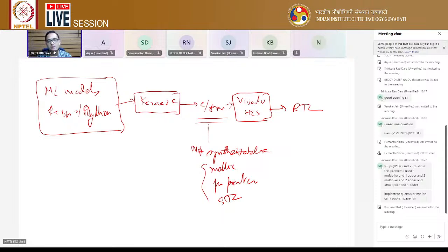Because if you make that array 1000, in the hardware you need a RAM which has 1000 locations, and out of that only 50 is valid, 950 is useless. So we have seen that most of the area was coming because of those arrays, which by default have the same size in all places, but which is not necessary by the code.